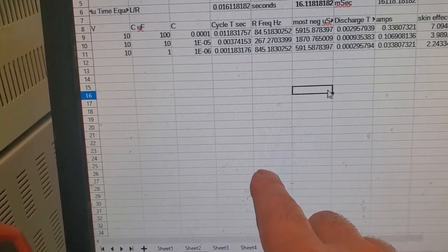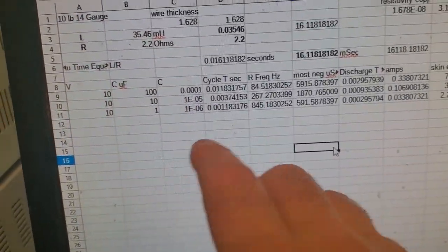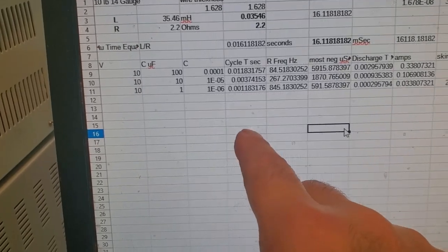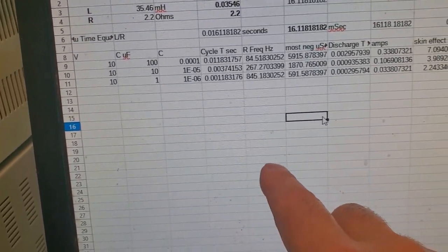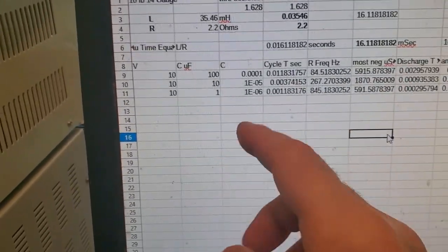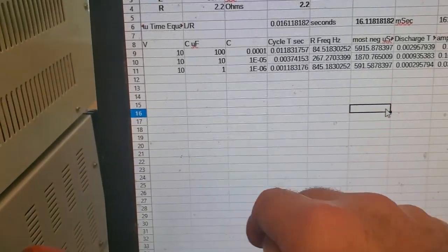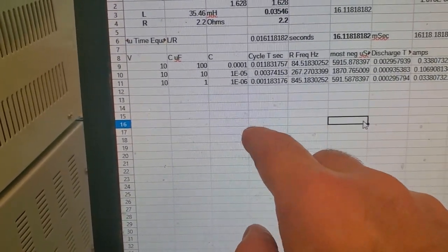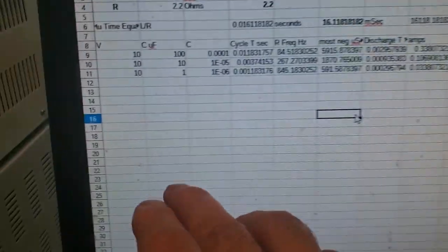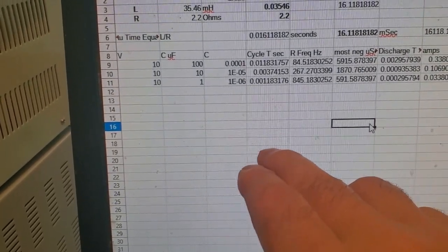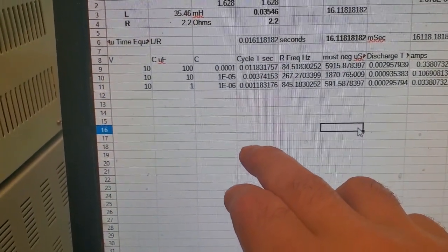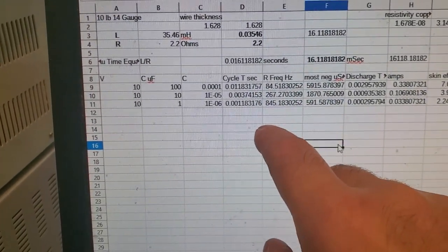And then it collapses. So what you want to do, well, first, if you just left the switch closed longer, to the most negative point, the coil charges to its maximal and then it discharges, the magnetic field is collapsing, and per Faraday's law of induction, there's a displacement current generated, a radiant if you like. And where does that radiant go? It goes right back into the cap, except it's inverting now because this is collapsing. So that's why the cap then goes negative. And then the coil goes to zero, the cap's now negative, and now the cap discharges again and charges this in the opposite direction, and the cap gets to zero, and then the coil starts discharging and now putting positive current,